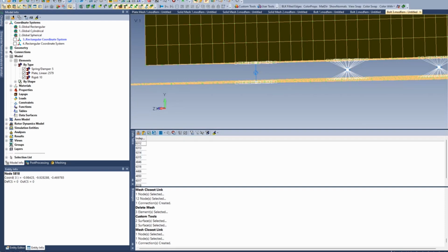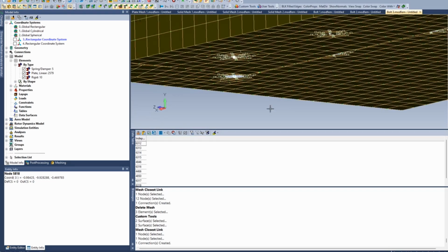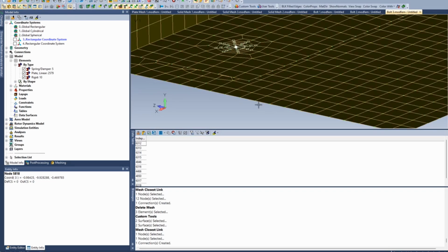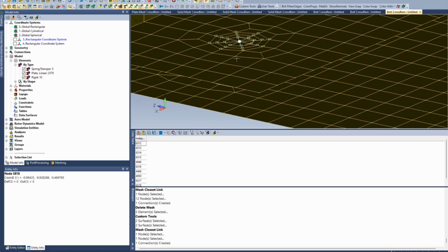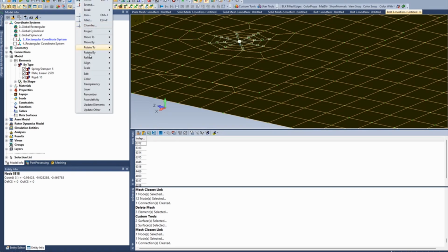Okay, and then the last one for now, at least, is what is the best method of modeling bolted connections for thermoelastic analysis? You would probably want to use beams. It's been a long time since I have done anything with thermal, and I don't know if you're talking about heat transfer or thermal stress, but there are some issues when using RBEs with thermal stress.